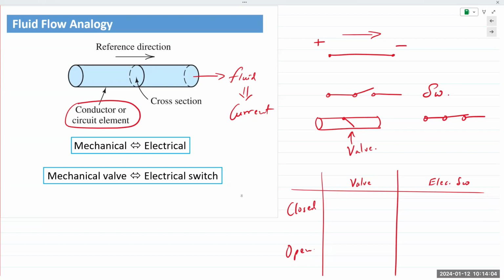Spark, small explosion. The reason is you have high voltage coming in there. The wire has some amount of resistance, but now you have provided a closed pathway or a closed loop for current to flow through. So if current flows through, it generates heat. If the wire is very thin and cannot handle that heat, it's going to blow out, right?